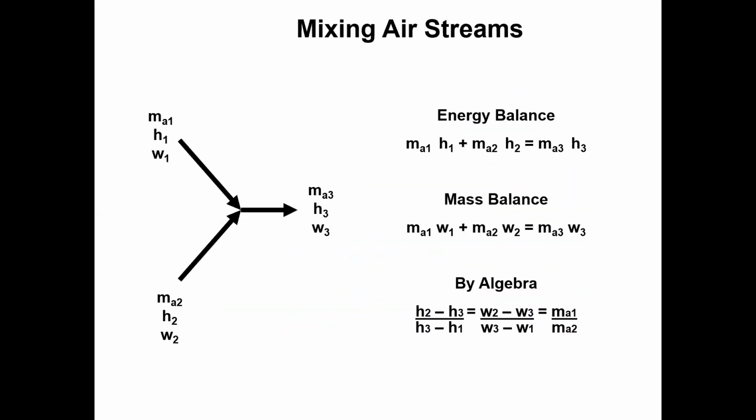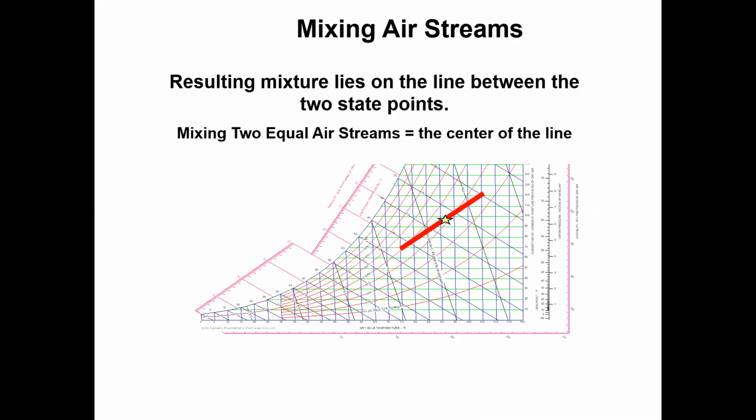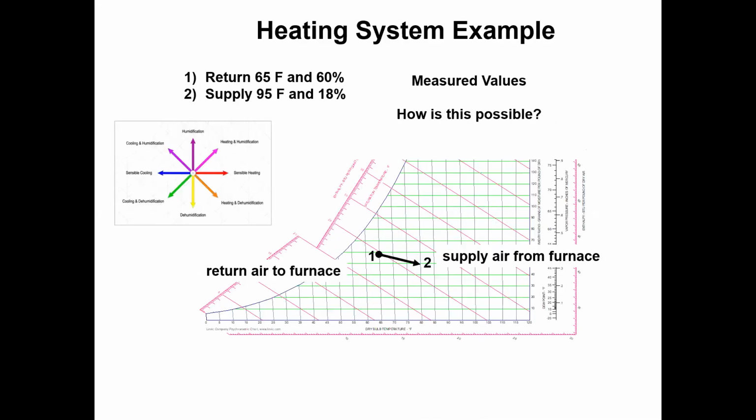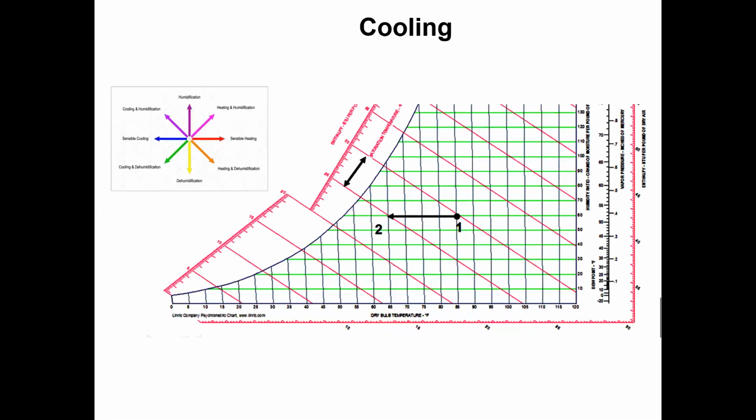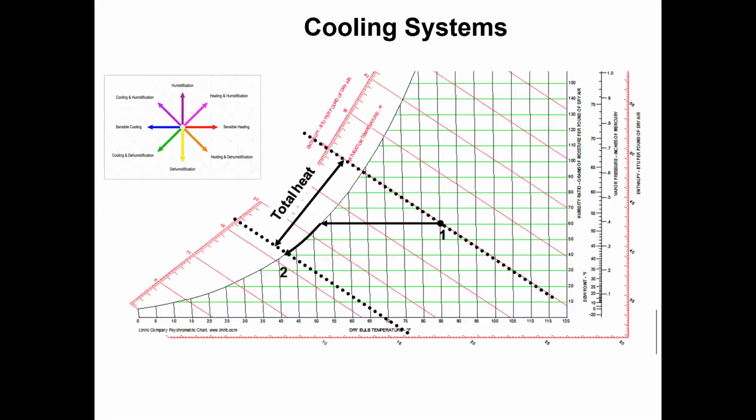Just go through these ones, and these are similar for an energy balance and mass balance. We get all these values from the psychrometric chart, and we have to calculate other things from different equations. Using those equations we can get this. Before going ahead to the heating and cooling load calculation of any commercial or residential building, we just need to know how to read the psychrometric chart. I just want you to go through all these lectures, and in the next lecture we will go for the heating and cooling load calculations.